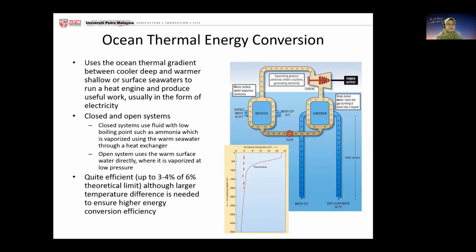Okay, where you have a type of gas, a fluid. So this one is driven by ammonia. If you ask me why ammonia, it has a low boiling point. If I'm not mistaken, something around -30 or -34 degrees Celsius, it will start to boil. So in this type of fluid, you only need less heat to boil it up if you compare that to water.